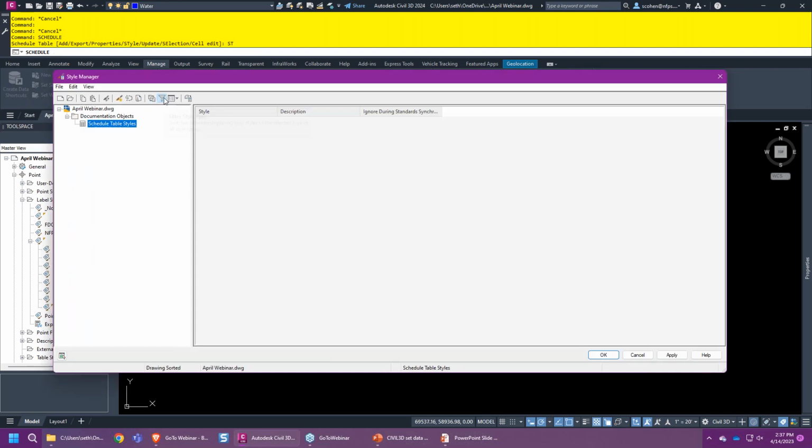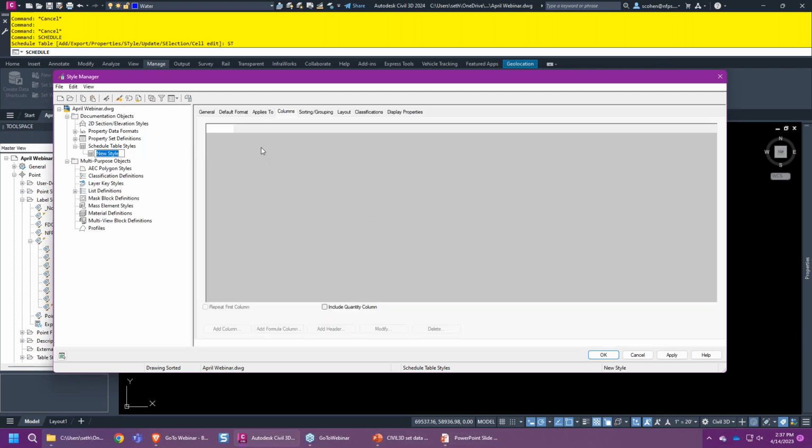But again, I could have just gone to property set definition and just grabbed it that way, right? Again, it's just doing that whole filter thing. I don't know why it does it, because it's really maybe 7 here. It's just a handful. It's not that hard to deal with. So anywho, what you do is just simply right-click on this here, okay, and choose new, all right? And for this name, I want to call this one the existing, and we'll do all caps here, EX utilities.